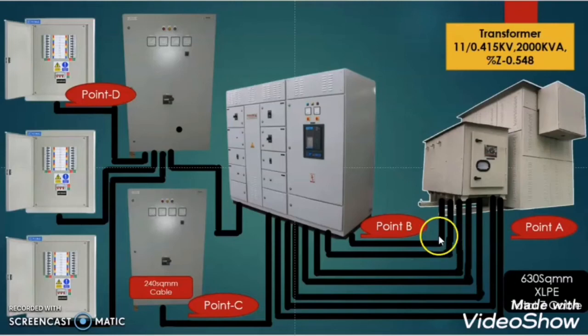Okay, 2 for red phase, 2 for yellow phase, 2 for blue phase and 1 for neutral. And the outgoing cable for this SMDB is 240 square mm cable. In the same way, I chose this cable as 25 square mm from the sub-main distribution board to the final distribution board.